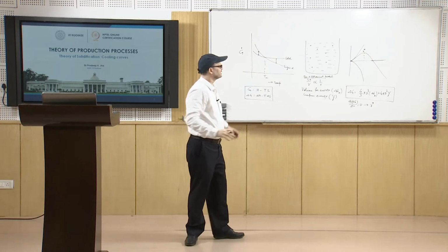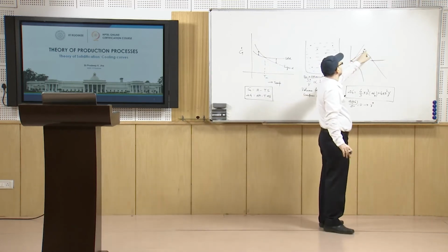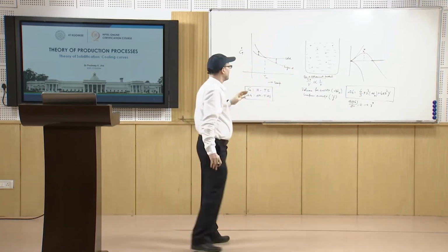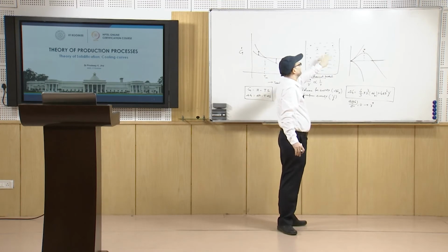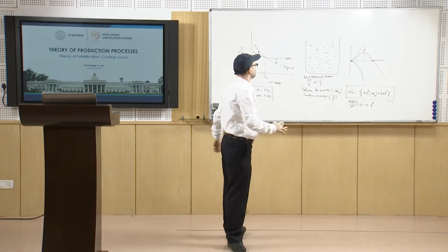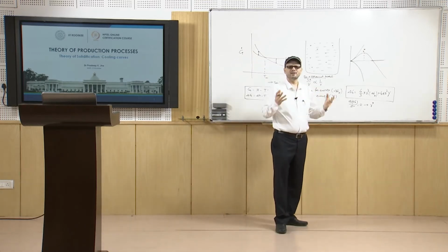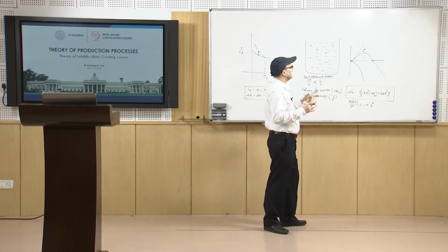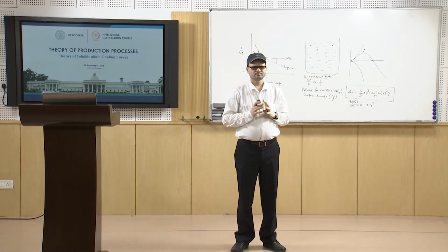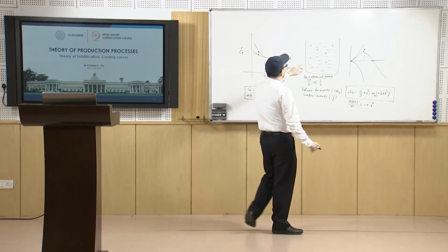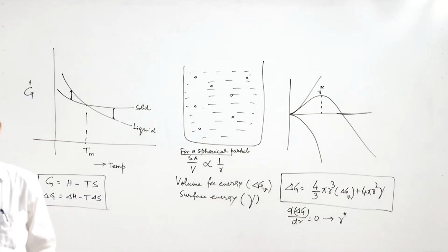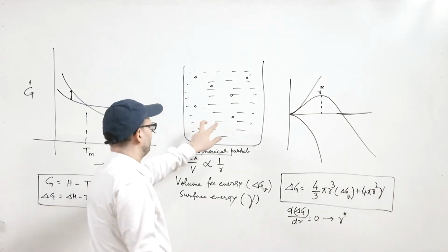Now, what we see in this case is that this is known as the critical radius. This is the concept of nucleation, because you will have the conditions at which the embryo will develop, and once it is able to stabilize, then we can say it has nucleated. Further, you will have the addition of atoms to it, and that is known as growth. Now, the thing is that you will have this nucleation at random positions. We do not know where the nucleation will be.